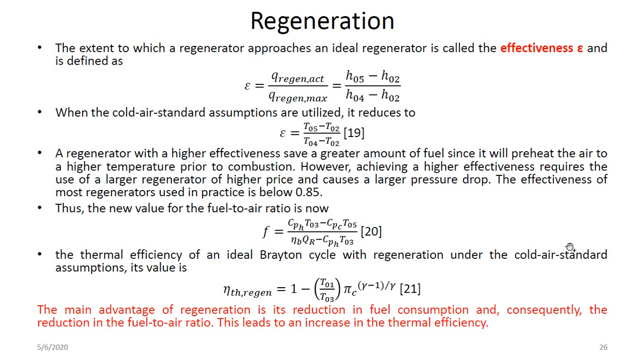However, achieving a higher effectiveness requires the use of a larger regenerator of higher price and causes a larger pressure drop. The effectiveness of most regenerators is usually below 85%. So the more effective you want to make it, the more money it will cost you.